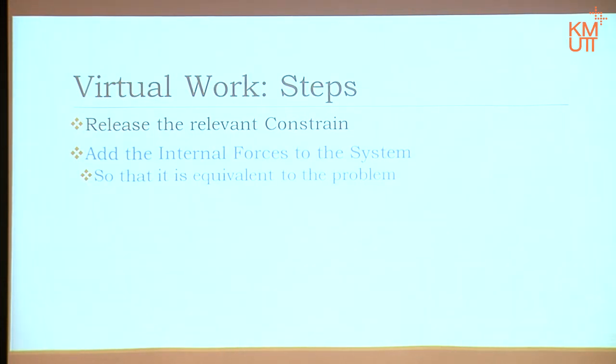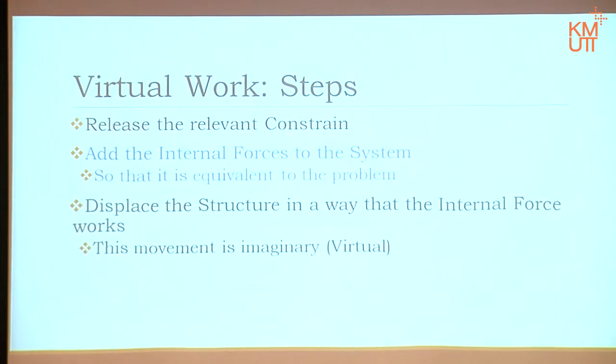Then we will have to add in the missing force, in this case the relevant internal force. In one case it will be bending moment, in the other it will be the shear force. We are not talking about axial here. Then it becomes equivalent again. Then we start to move the structure a little bit, or in this case displace it.